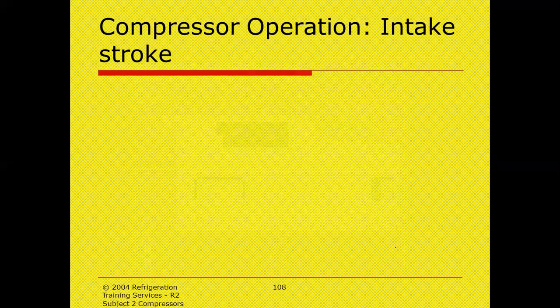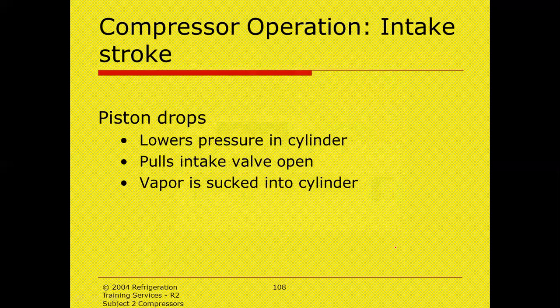Before that, first we'll see how the compressor works. On the first stroke, the piston gets down. Whenever the piston drops down, it lowers the pressure in the cylinder.